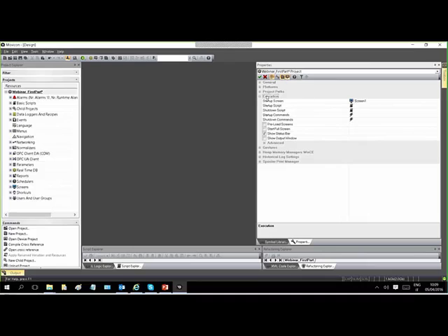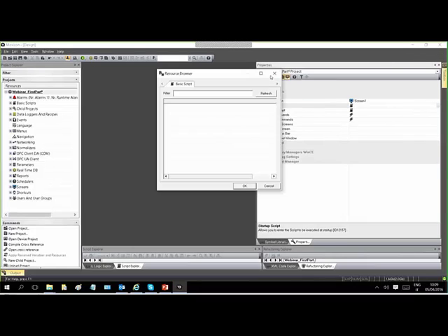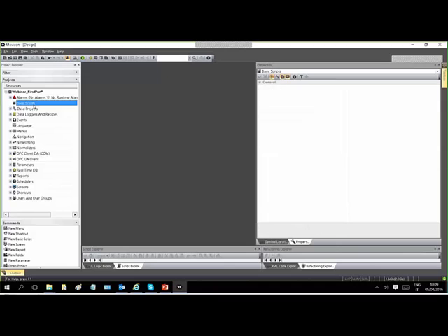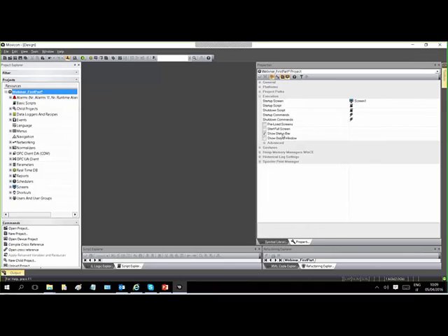Okay, now it could start to be interesting: the project execution properties. Here you go and set, for example, the startup screen. It is the screen that opens when you run your project. It could be your main page, could be your overview screen of the application. Startup script: you can call here, for example, a script that you defined in the script resource to initialize some variables when your project starts. Shutdown script is the same, but when the project shuts down, you can stop and unload the script from memory.